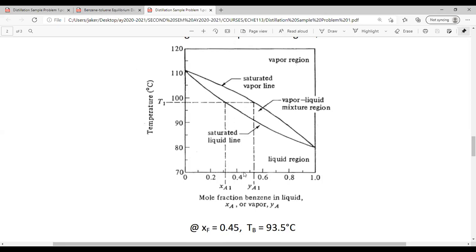By the way, class, it's 0.45, don't follow that one, this is a different line. So it's 0.45, and here you go up, and if it's a saturated liquid, it should be in here. It's about to boil in here. You have to stop in this particular curve, the lower curve, because this is your saturated liquid line, giving you the boiling point of your liquid.